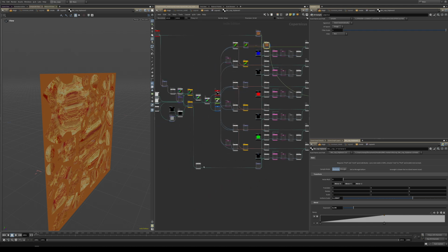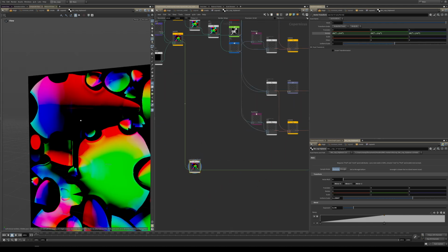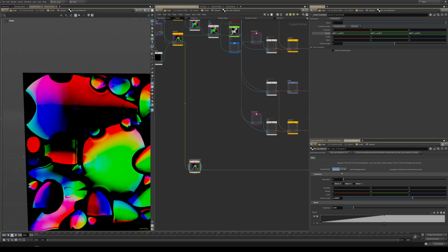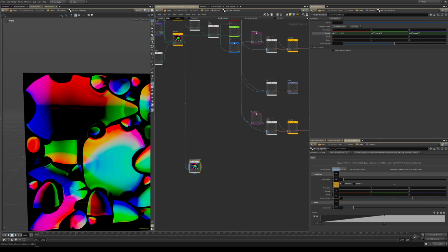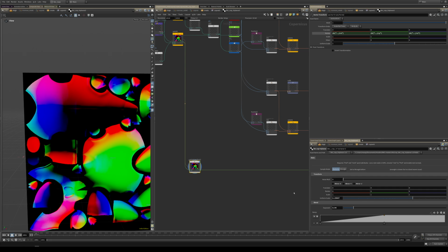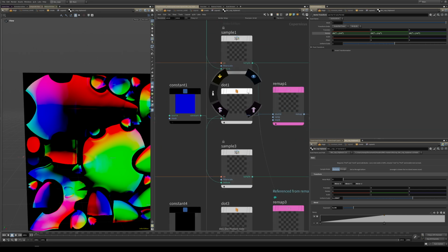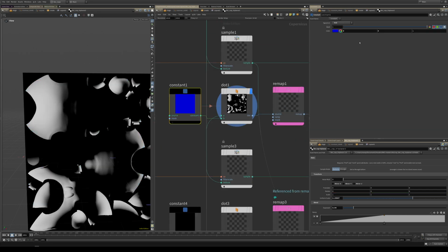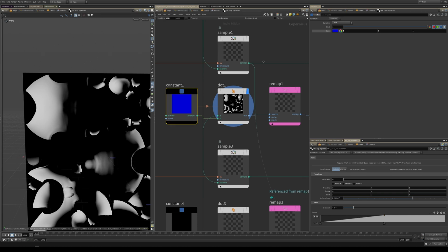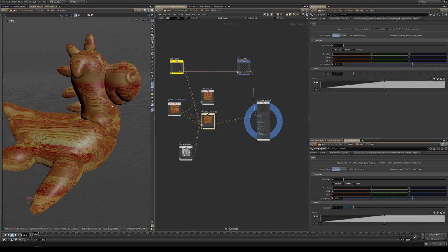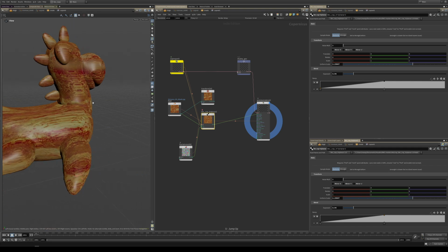So we need to take our normals, and again here we have our rotation control. We take those normals and do a dot product with the direction of our axis that we want to look up. In this case, if we go back up, it's this direction, Z plus, right?